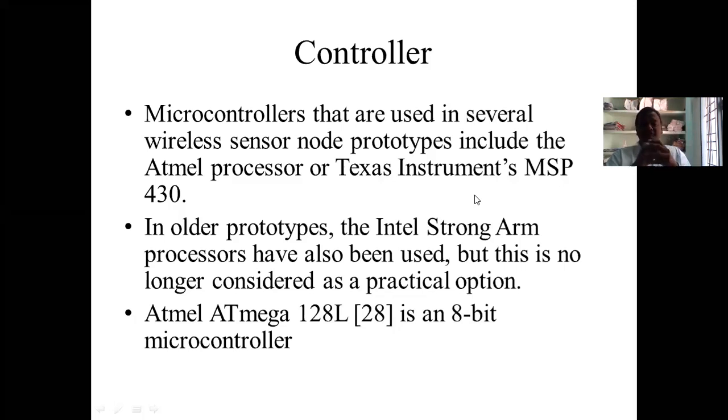But one strong piece of advice while you are using the node: once a sensor senses, then the processor can start, and once the processor starts, then it should communicate. So you do not keep the controller and the communicating device in the on position.